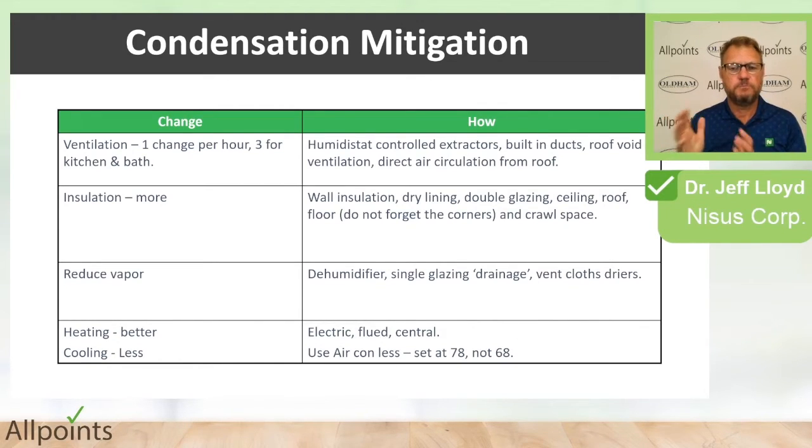And making sure your insulation is good in the walls is great, and having some form of ventilation is good. Or if you can't have enough ventilation, or if it's really cold outside, so you just want to try and avoid having windows and doors open, for example, the use of a dehumidifier is a good idea. And running air conditioning, an HVAC system during the summer, will give you dehumidification in the home, but typically not in the crawl space and the wall voids. So, bear that in mind.